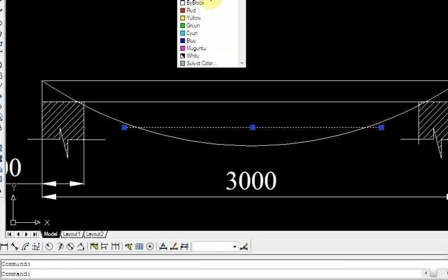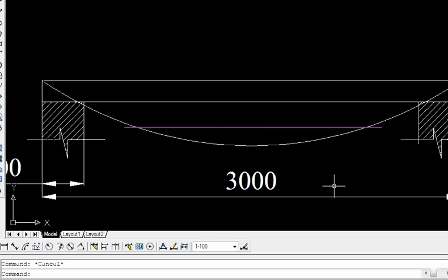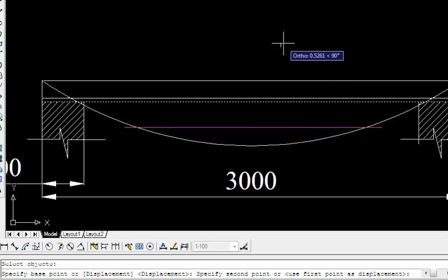This is nothing but a reinforcement I am thinking, and this should be given like this, which will lift this deflection upward. So the main bar is given at the bottom here, so we can shift it here. The clear cover is given as 20 mm.